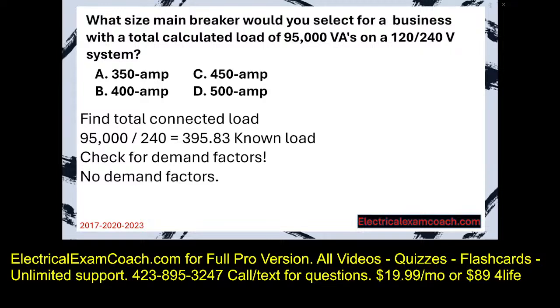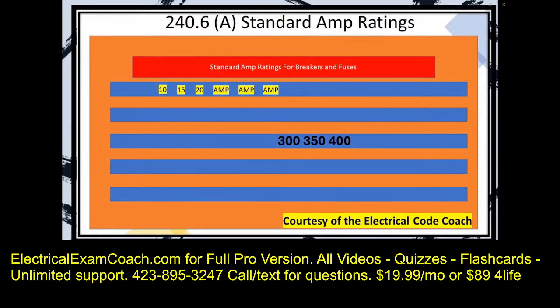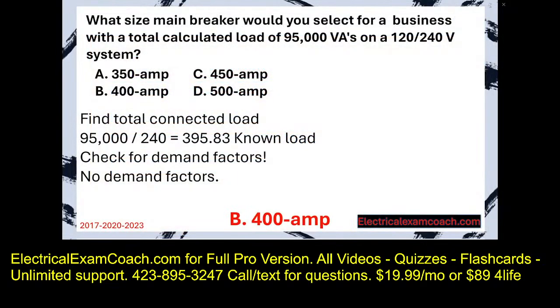Factors. Now we head to table 240.6(A) and we choose the next standard size breaker. And this would be a 400 amp breaker. This would also be a 400 amp service.